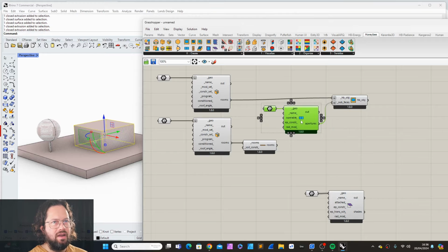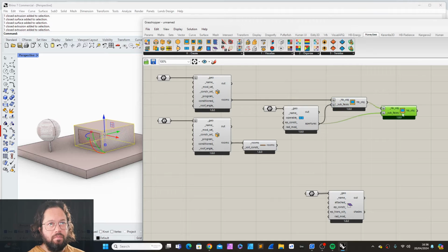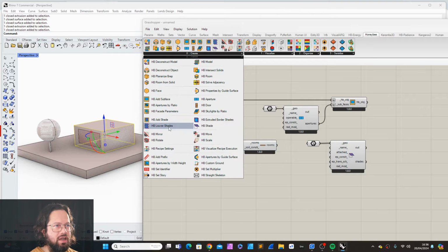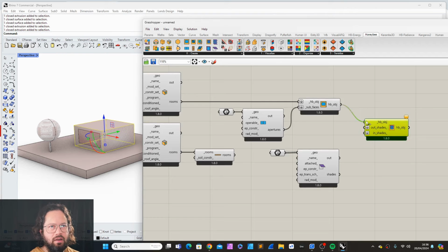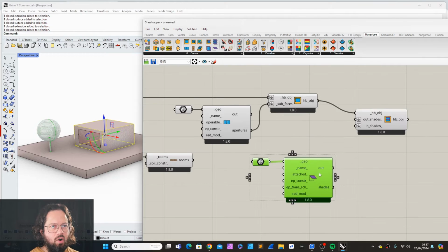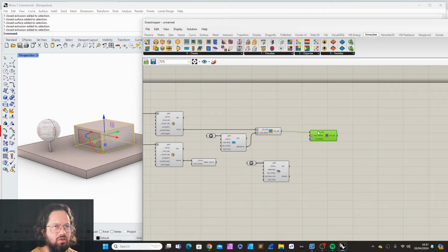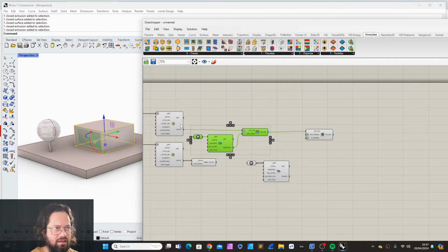Now I have added my windows or doors. Both. You can both plug this in here. I like to separate this a bit, so you could also have another one, attach this, and then add your doors so they are separated. We can add a shading, Honeybee add shade. So it's always the latest tool in the chain, which is the current version. These are done basically.